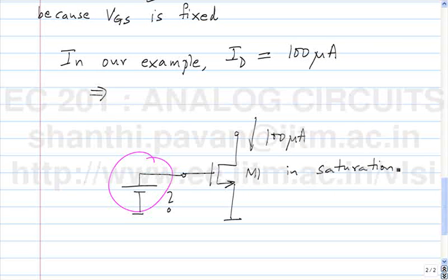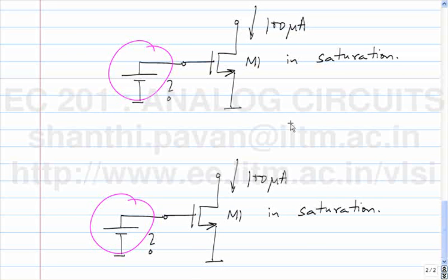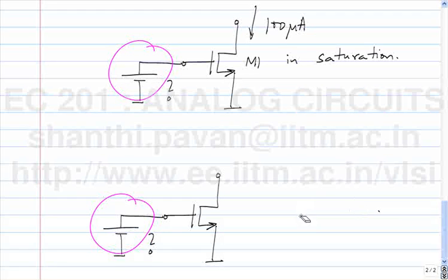Alright. So can somebody come up with a smarter way of doing it without having to do any math at all? What are the conditions that have been put? First of all, you all agree from these two gentlemen that we certainly need a variable voltage source. This is what I would do. I need to keep M1 in saturation, correct? So what potential should I connect the drain to? I can't obviously leave the drain floating. So to keep the transistor in saturation, what would I have to do?